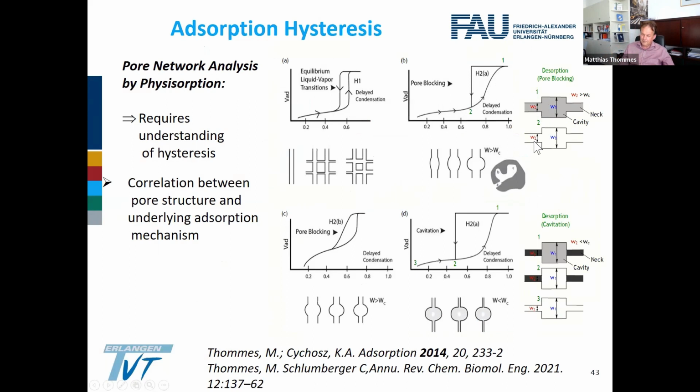This is quite different when we go to the case where so-called cavitation happens. In this case, the necks are much, much smaller, and they're below a certain critical size. When they're below a critical size, we reach the pressure of the liquid-vapor spinodal of the condensed fluid in such a pore.